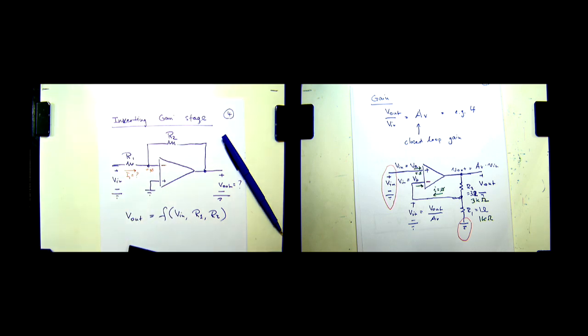And so again, it means that if you went there with the voltmeter, you would always measure that the voltage here with respect to ground is zero. It doesn't mean that there is actually a wire connecting the two. If you put the wire there, it's not going to work anymore. So don't put the wire there. Even without the wire, if we have negative feedback, the voltage here is going to be zero.